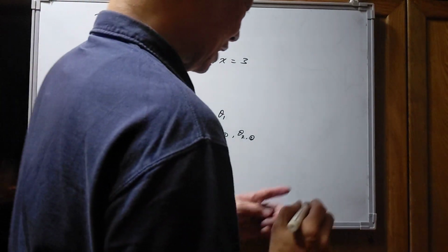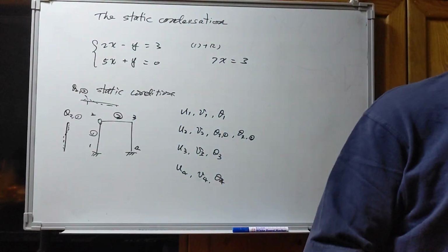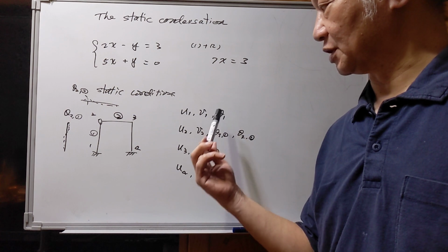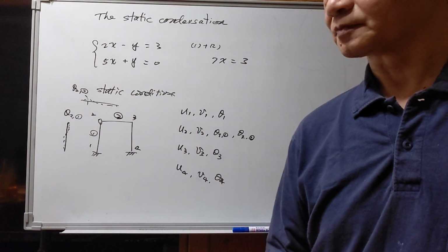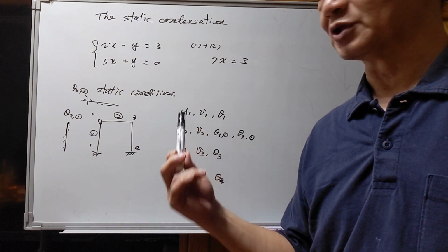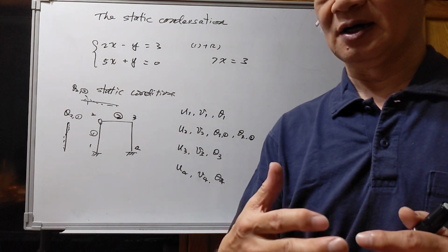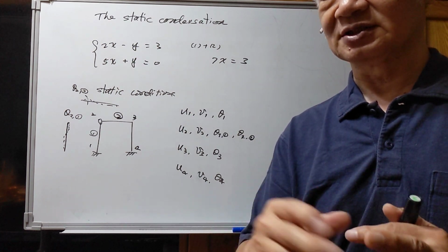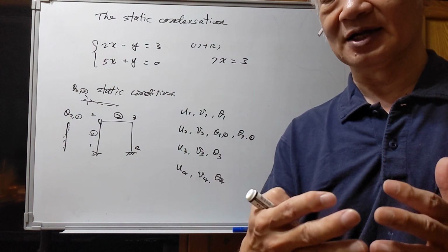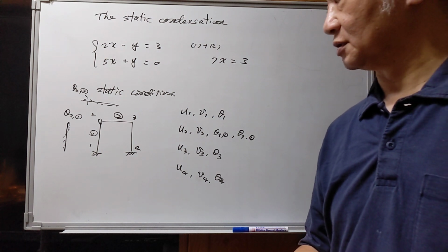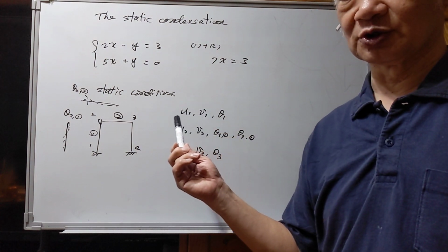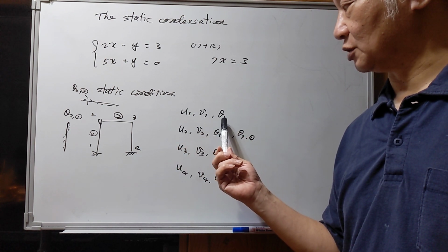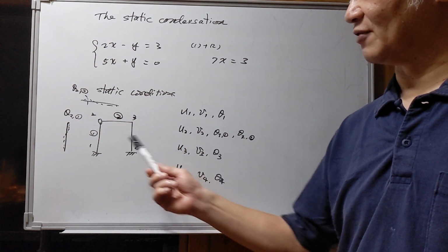Okay. The other three joints do not have pin connections, so we can use only one rotation. For the nodal displacement, since the joint is assumed to connect all the elements connected to it, we can use only one set of nodal displacements for each nodal point. And we need to assume the rotations theta 1, theta 3, and theta 4.